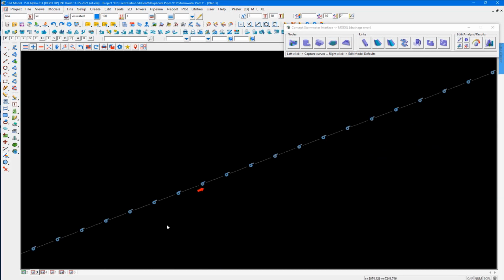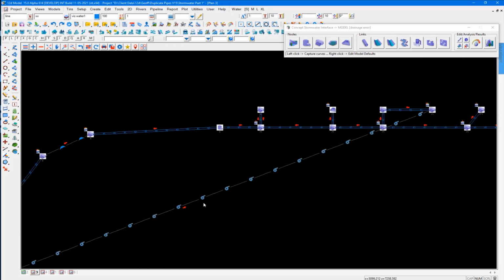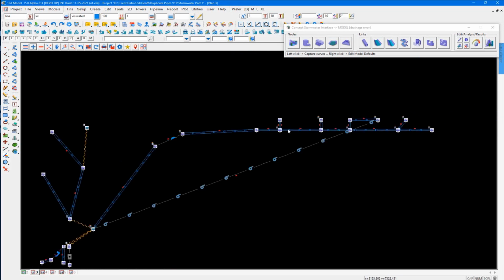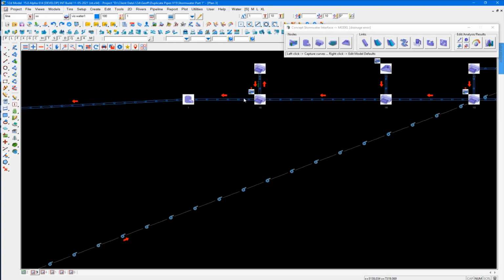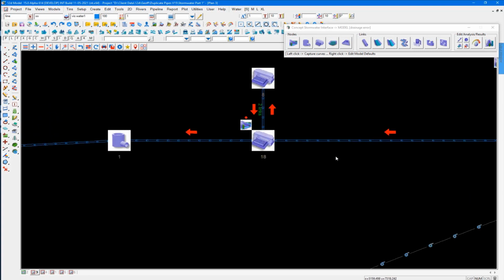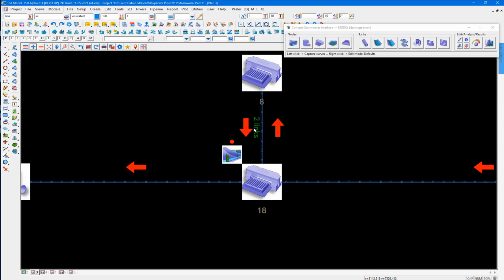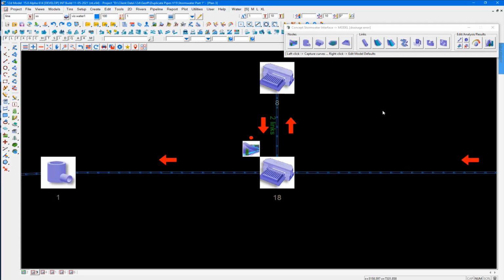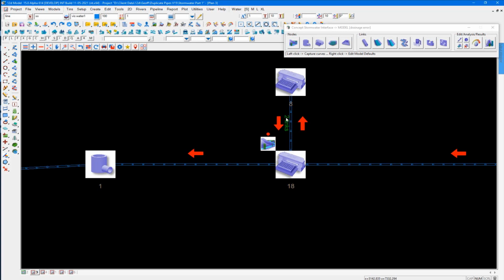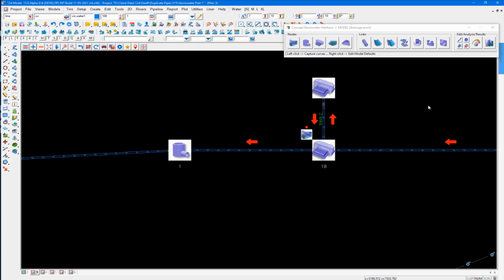It looks like the pump is flowing in the direction it should be, so this looks like a pump to me. So suddenly all of these things that we could see before that weren't obvious to us start to make a little bit more sense. You can actually see here that we've got 2 links running between these 2 nodes, and they happen to be running in opposite directions, which is probably not really what was intended. So that could be a typo in the invert levels that someone needs to go and have another look at.